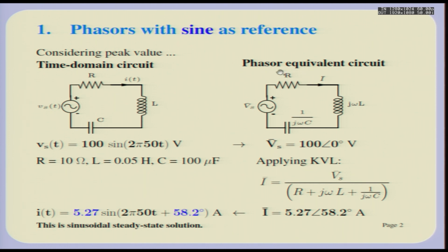the phasor domain. Now, when we are talking of phasor domain, this is essentially replacing the L's by j omega L or SL, but with s equal to j omega. I have in a previous lecture shown you that you can in fact just by plugging in s equal to j omega get the responses, infer the phase shifts and magnitudes when you actually apply inputs like e raised to j omega t or even sin omega t or cos omega t.